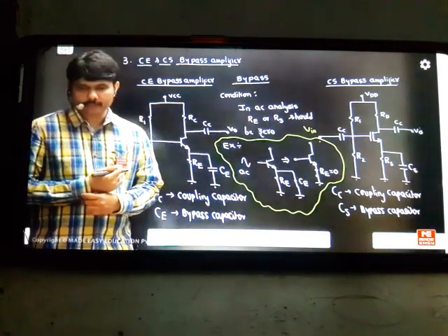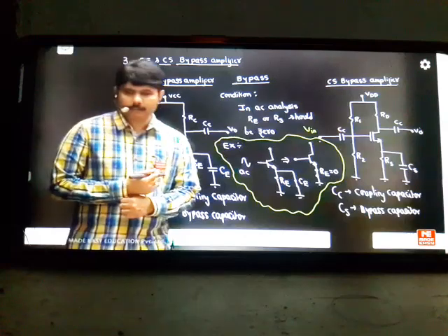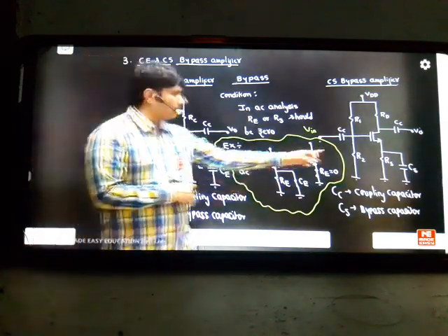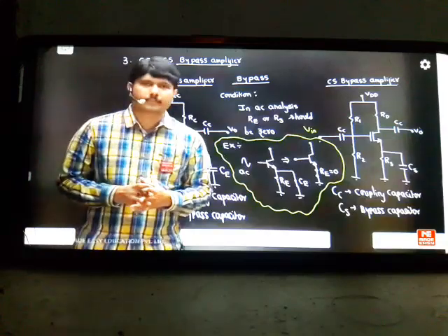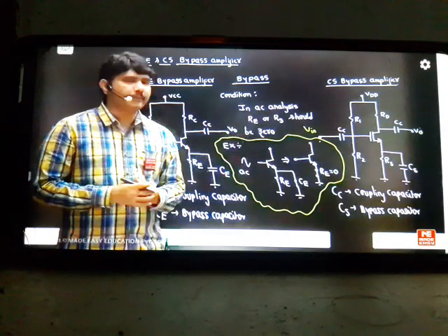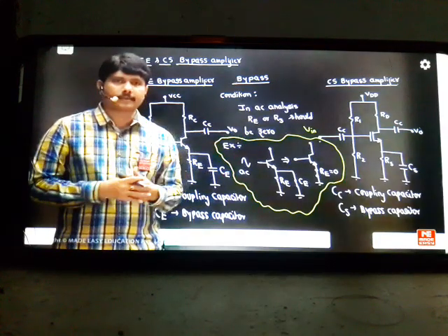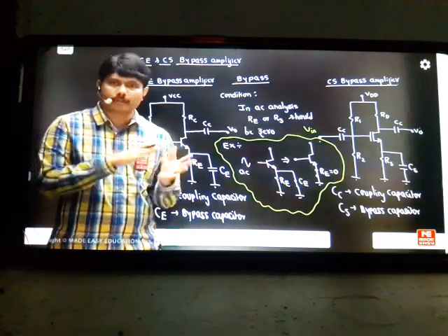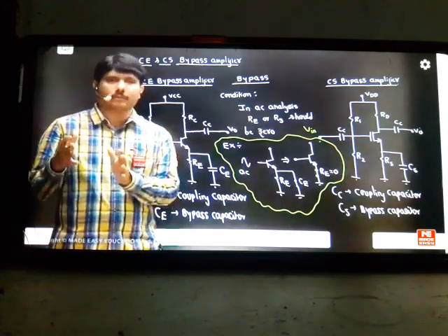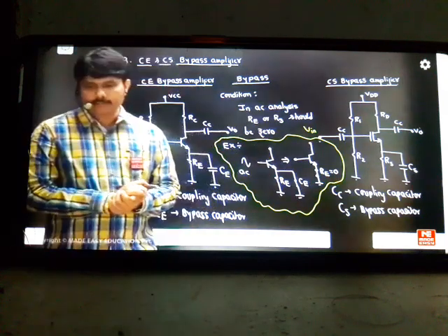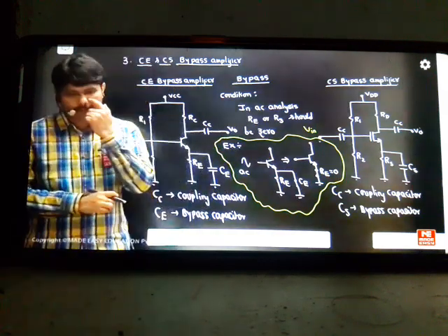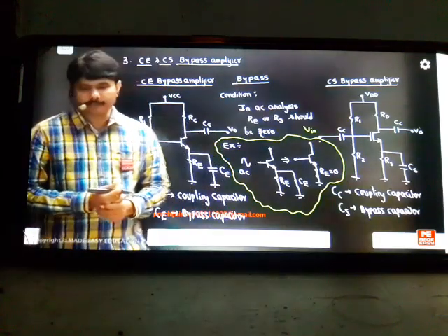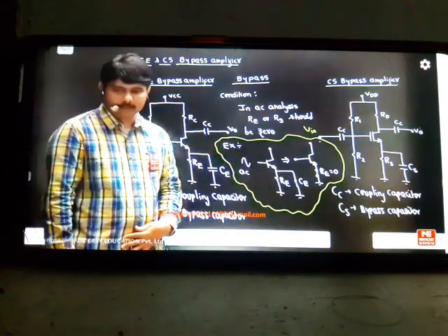If you don't need the resistor, why are you not directly removing it? You can't do that. The resistor you can keep, because there are some reasons for that. If you directly short the resistor, you can do that also. But when you do that, the circuit becomes a fixed biasing circuit. Fixed bias in DC analysis is unstable in nature. Correct? If you want to make it more stable, the resistor should be present in DC analysis. For AC, it has to become short. So we have 2 issues there. DC wise we want it. AC wise we don't want it. That is the reason we kept it like that. DC wise we want it for stabilization. AC wise we don't want it because gain is reduced. If 14A is not opening, I will complain to them. They'll try to re-upload it. No problem. Thank you very much for giving the feedback.